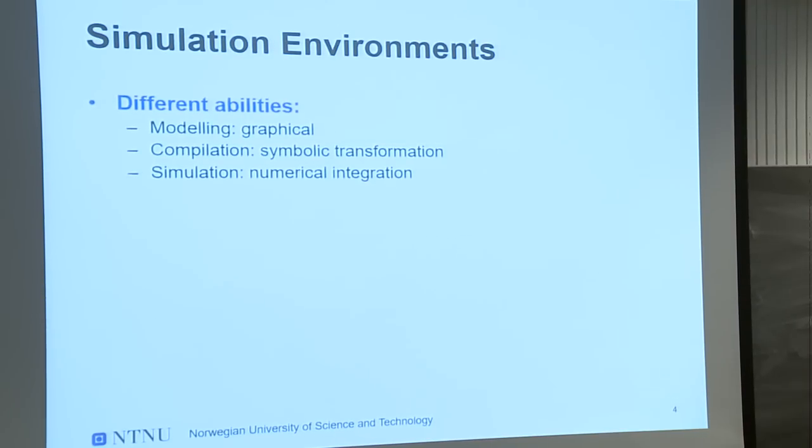You can compile it, and the whole Modelica environment is symbolic by definition. So if you have a big system, Dymola, as an example, simplifies the system for you. It does a transformation and allows you to get the solution more easily afterwards. And for simulation, it is a numerical integrator and a flowsheet solver. Now, you will probably ask yourself, that is something you can also get with Simulink, but you will see afterwards where the advantages of Modelica lie.